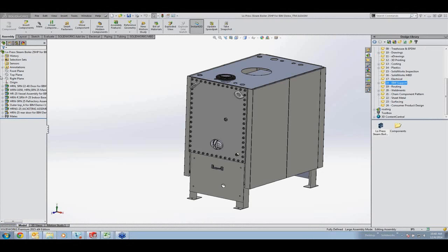So I have a length, a quantity. There's 2 quantities for that one, so there's another one here on the right side. It also shows my bends. So here I got a horizontal bend, 90 degree, elbow, the type, the component type. I can also create balloons for those as well, just like a standard assembly.